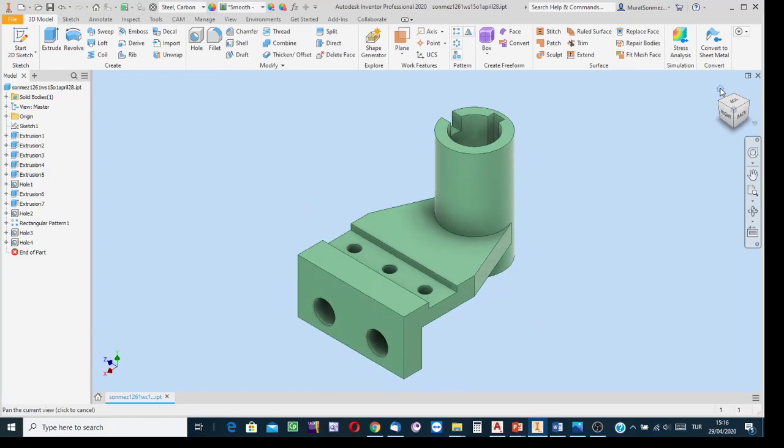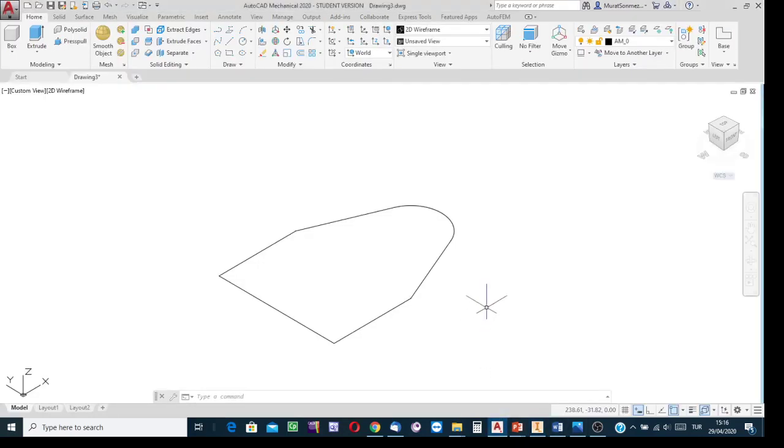I selected that way to follow and created the model of the object in Inventor. I had this profile first, then extrusion, and then applied the extrusion process to create the cylindrical extensions. Then I created this part, then the channel, this truly extending channel and this blind channel. I'm going to follow the same stages, but using the tools of AutoCAD. Life will be relatively difficult for me, because AutoCAD is not a new generation software.